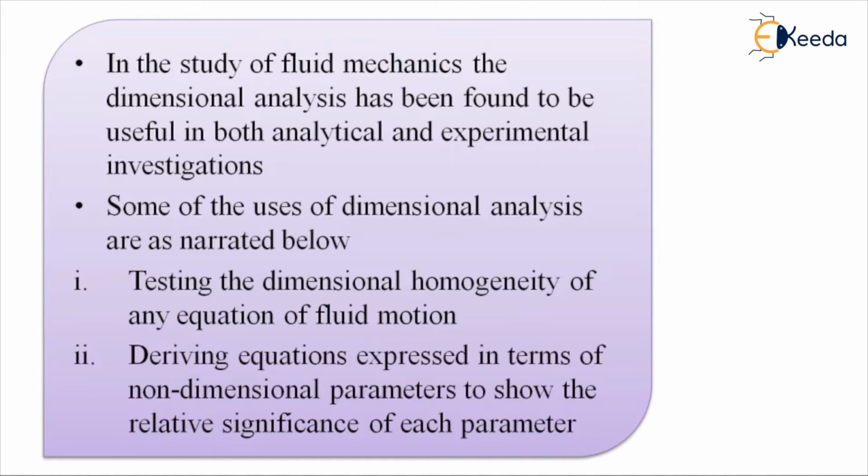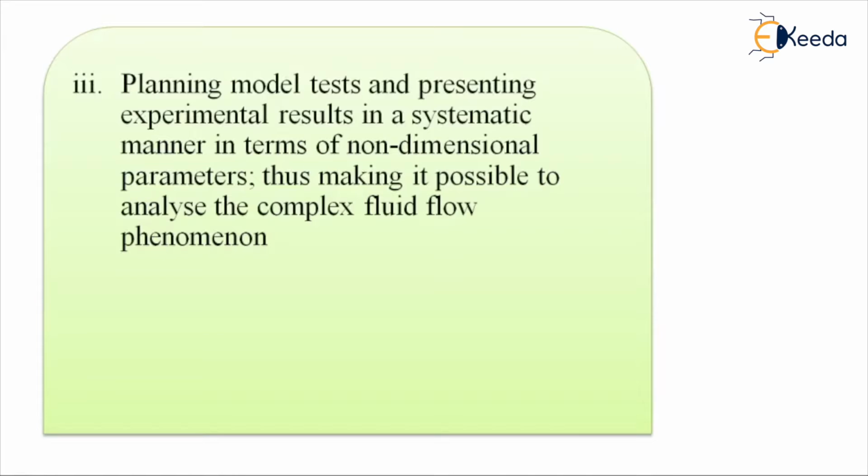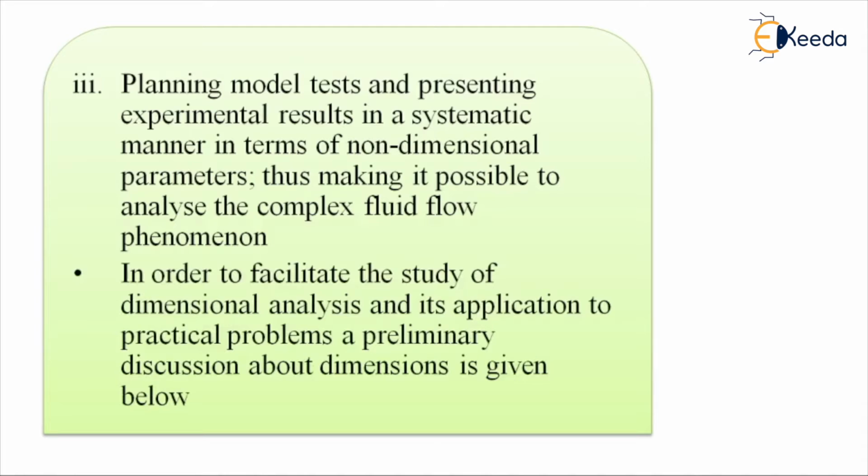Second, deriving the equations expressed in terms of non-dimensional parameters to show the relative significance of each parameter. And the third one is planning model tests and presenting experimental results in a systematic manner in terms of non-dimensional parameters, thus making it possible to analyze complex fluid flow phenomena. In order to facilitate the study of dimensional analysis and its application to practical problems, a preliminary discussion about the dimensions is given below.